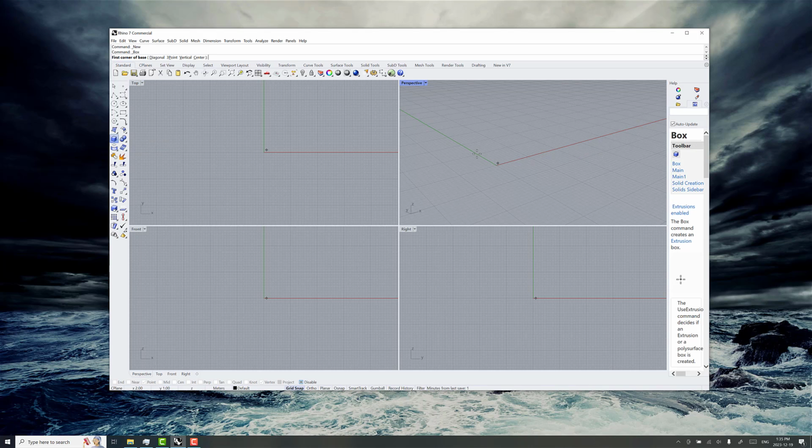creating a system with the frame at the bottom and the aft, the transom of this little box barge. So it's all arbitrary. We're going to arbitrarily make this a 20 meter by 20 meter box. So we'll go Y of 20. I'm just looking down here at the coordinates here. You may find that grid snap is helpful for this as well. So we'll go to Y to minus 10 on the other side, and then we want X 20 here. So there's our little box, and then we will, looking at the Z view here, make it 2 meters tall, and there's our little surface.